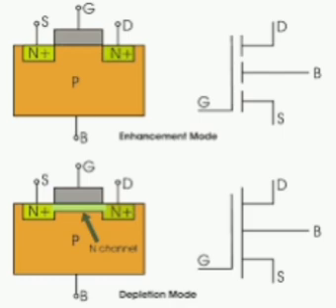Saturation, active, amplifier, reverse active, attenuator. A transistor has excellent transistor action if the emitter is heavily doped in comparison to the base. Base width is kept much smaller than the diffusion length of carriers.